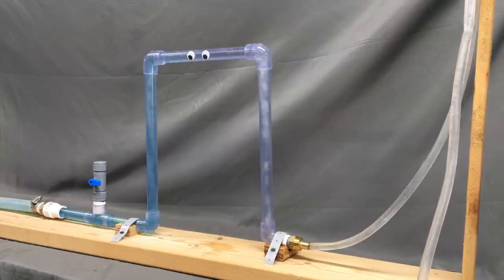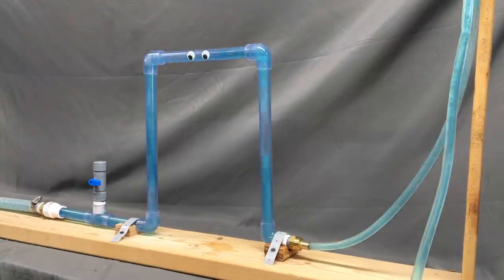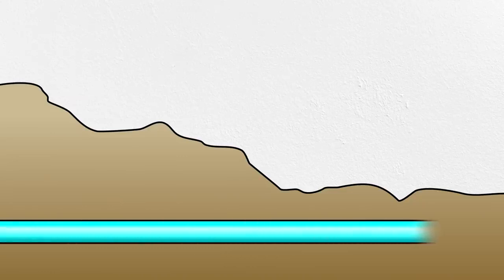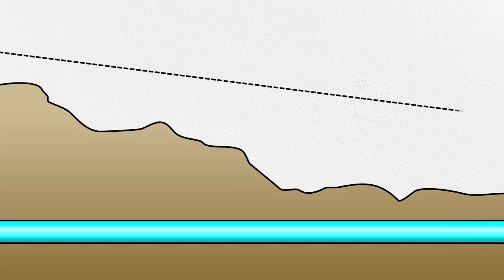The fluid starts at one end with a certain amount of it, and the flow rate depends on how much energy gets lost as it makes its way to the other end. Engineers use a graphical tool called the hydraulic grade line to show this visually. The line represents the potential energy available in the fluid at any point along the pipe.